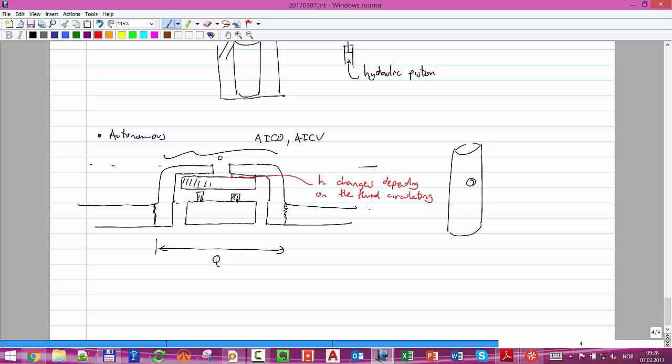Okay, for example, if it's gas that has low density and low viscosity, it closes, and if it's water with high density and low viscosity, it also closes. Okay, and it won't close completely. It will still keep some space to circulate, but it opens when it's oil that has a medium and a high viscosity.